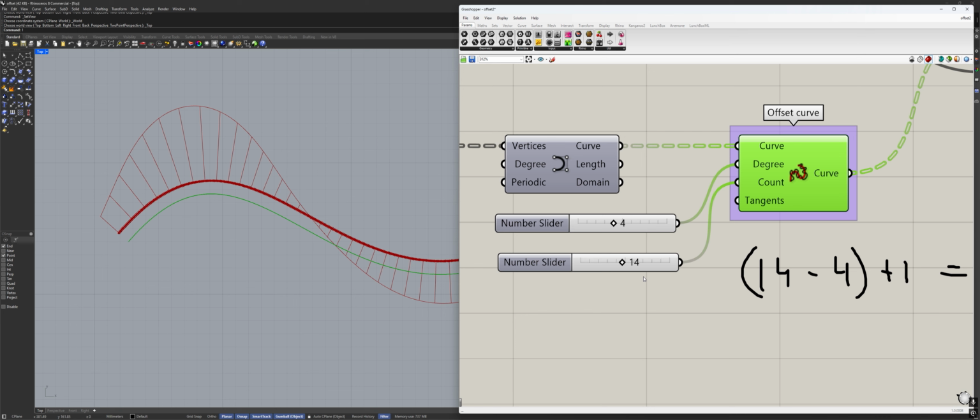Now, Grasshopper, in comparison to Alias, even though it operates with the same math and the concept of NURBS is literally the same, the way we treat it and how it visualizes information is quite different. So you probably remember that in Alias, you can't go more than the power of 9, or degree 9, for a single span curve, right? As well as surface. Well, Rhino can give you an option to go beyond, but not necessarily, because actually you define the amount of control points, but you're not specifying spans.